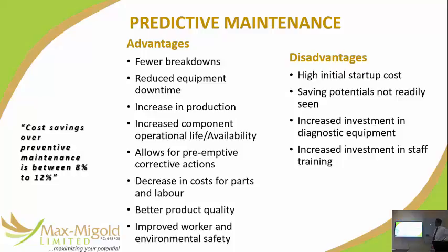So I believe that the advantages and disadvantages are pretty much straightforward. One major disadvantage is the high startup cost. Putting up those inventories, logs, actually enforcing quality of those reporting, having the tools to do them. For example, oil test, thermography. There are things that most people don't think about buying. Those testing kits are very expensive.